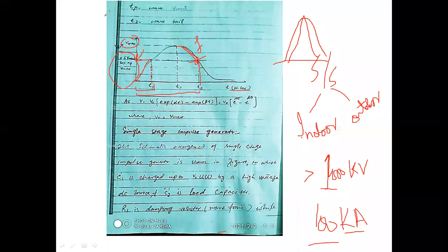Too high voltage levels are immediately chopped by the breakdown of the insulation, and therefore traveling waves with steep wave fronts and even steeper wave tails may stress the insulation of power transformers or other high voltage equipment severely. For this purpose we will study insulation coordination. There must be some coordination between the insulation level and the protection equipment, the lightning protection system, surge arresters. Different kinds of losses will damp and distort the traveling waves, and therefore lightning overvoltages with very different wave shapes are present within the transmission system.